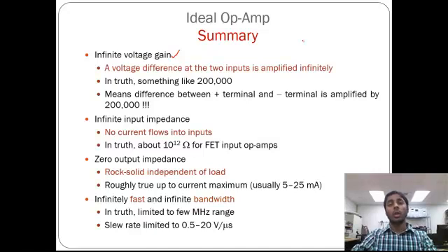We are also aware that no amplifier can amplify greater than its power source. When we talk about power amplifiers, the output voltage of any amplifier will not exceed the maximum power source. Let's say, for example, if your DC power source is 15 volts, the output of the amplifier will not exceed 15 volts. The maximum voltage you can get is 15 volts. At the same time, the negative voltage you can get is negative 15. So that particular amplifier has a very huge gain in order to maintain that.